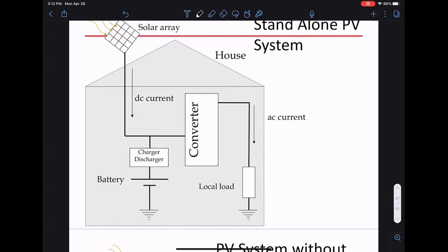Then you convert back to AC to go to your servers, computers. But at the end of the day, your computing service really needs DC, so you convert that AC to DC again to power your computing servers. So there are many levels of conversion loss. This is a so-called double conversion loss in data centers. And this can also happen in electric vehicles.